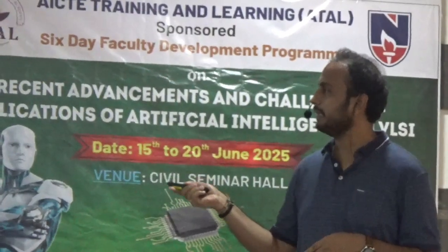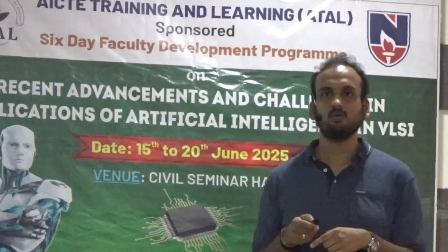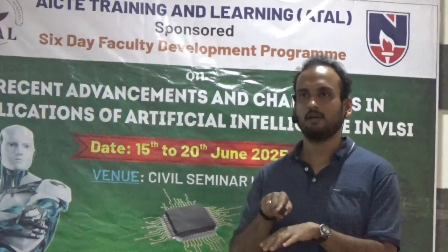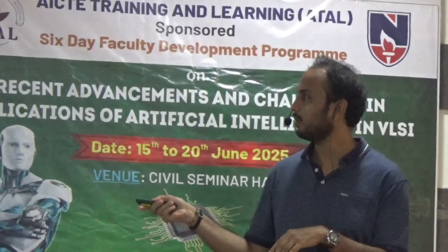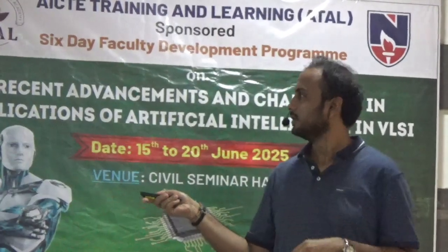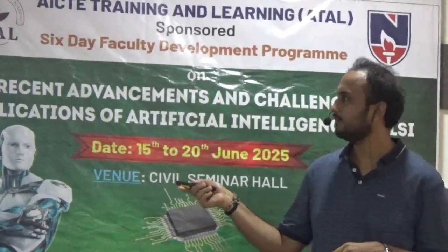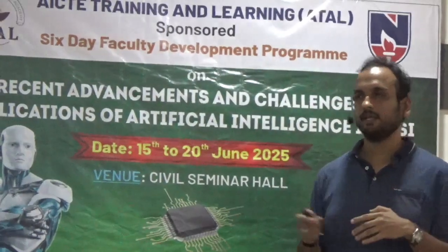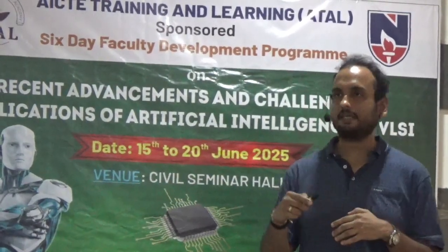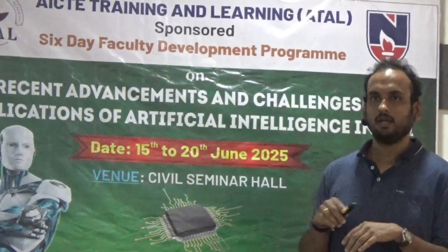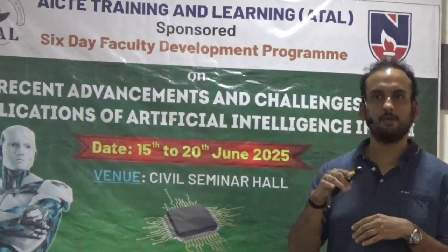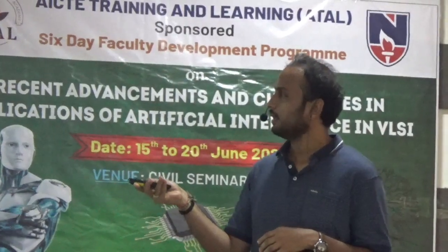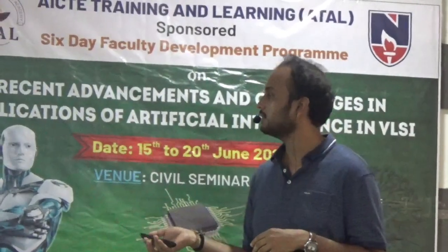And this is the complementary FET, basically NMOS and PMOS designed on the same structure. If you see, NMOS is on the bottom side and PMOS is on the top side. And then this is very futuristic, 3D VLSI, which they are trying to fabricate. The thinking is to fabricate different transistors at different levels, not on the same plane but on different planes. This is how the evolution of different transistors happened in the last few years.